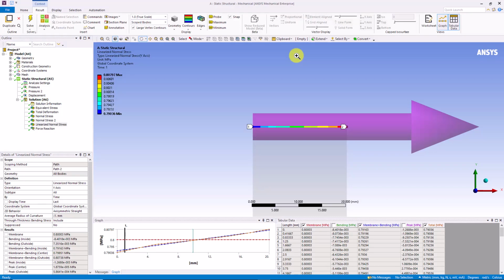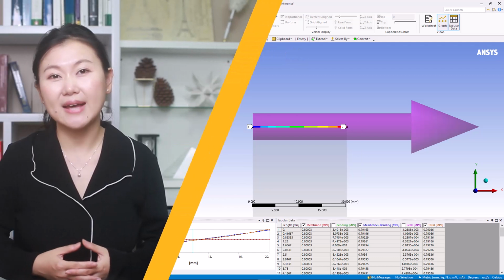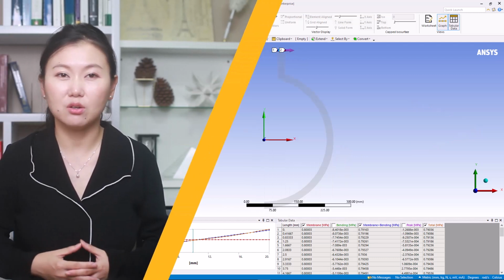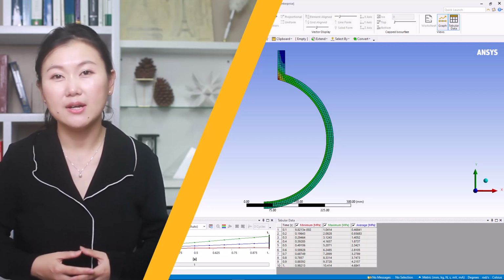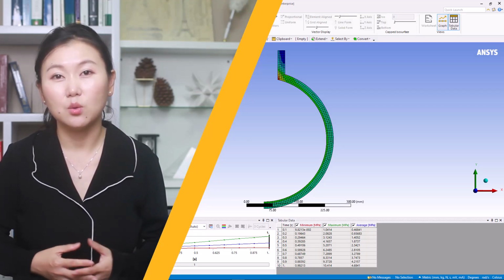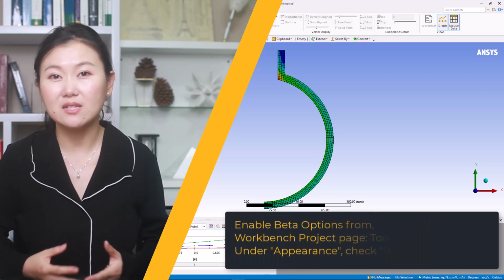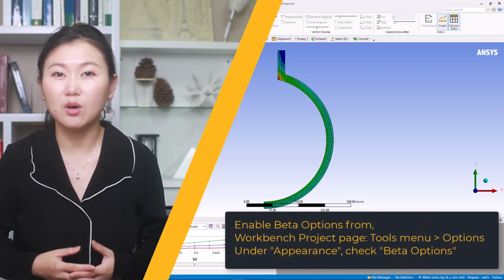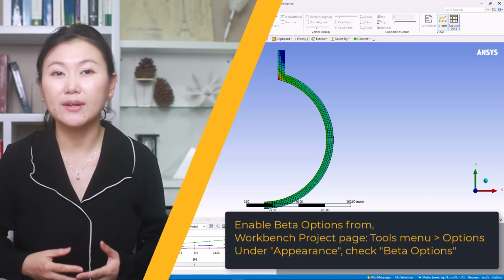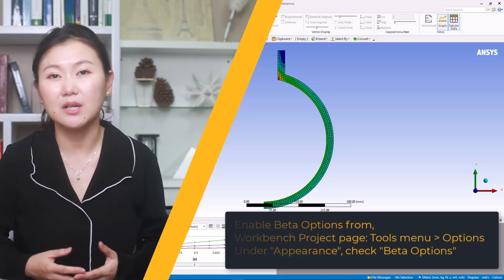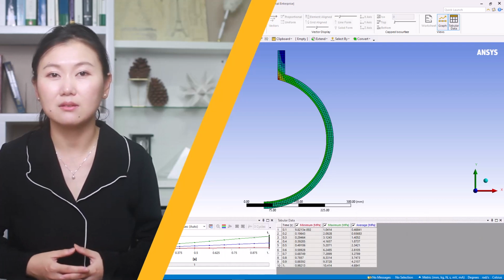of the pressure vessel. Although the results of the 2D axis symmetric analysis are two-dimensional, it is possible to visualize them in the form of a 3D model, thanks to the beta functionality within the symmetry tool. With this feature, the results are revolved around the axis to produce the 3D display, which can be helpful when conveying results to those not familiar with finite element analysis.